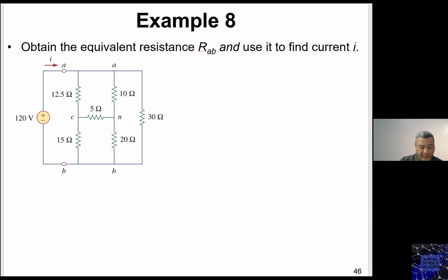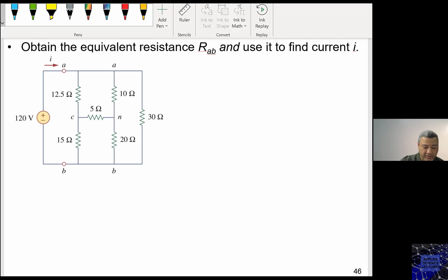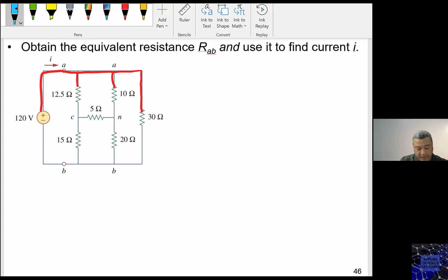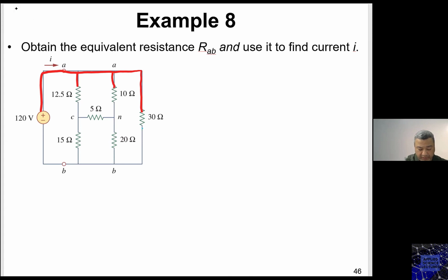Now, if I look at this circuit and I do the coloring again, coloring is very useful to you at the beginning of solving circuits, to make things easier for you to know which nodes are connected, or which components are connected to which nodes.